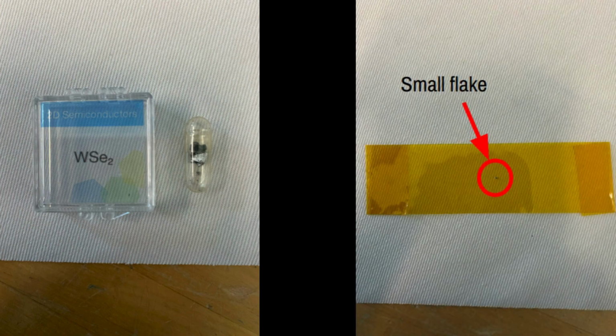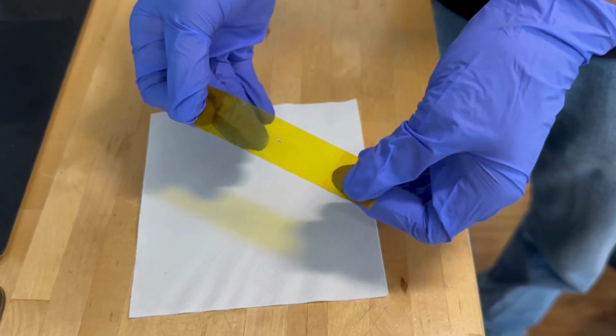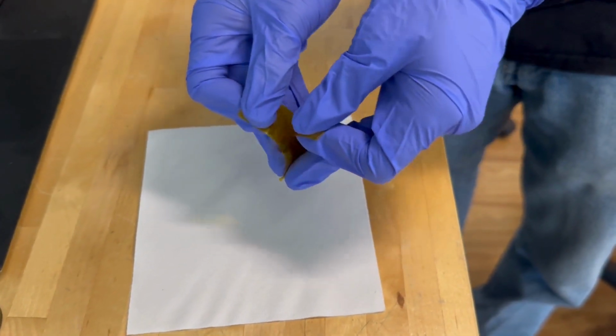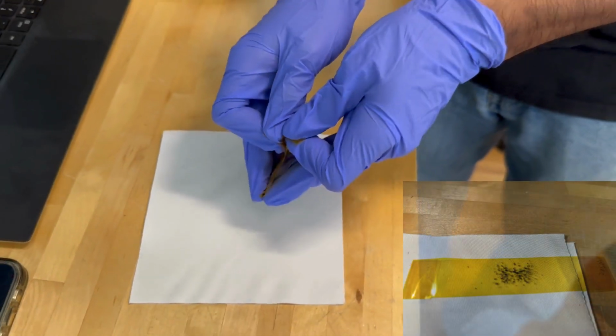First, a desired material is bought in its bulk flake form. A tiny piece is transferred onto a selected piece of tape. To mechanically exfoliate, the tape is pressed and peeled apart a tunable number of times, causing the tape to look cloudy with thinned flakes.